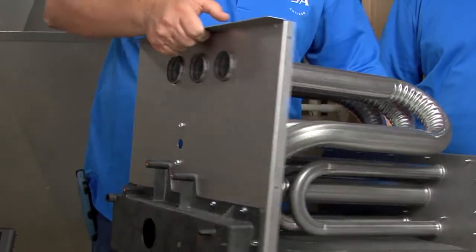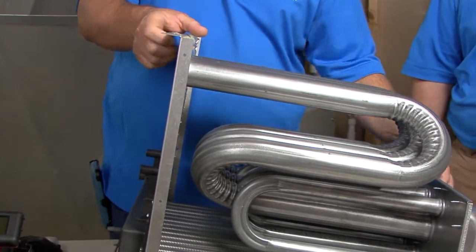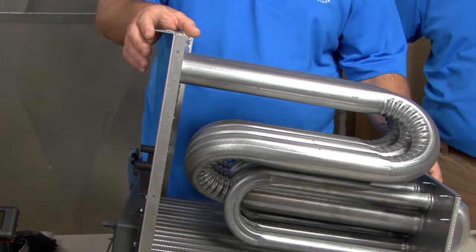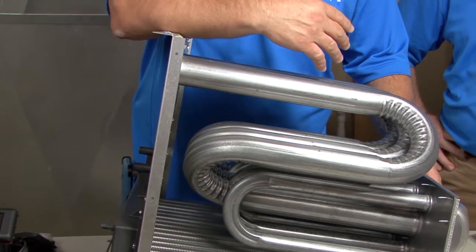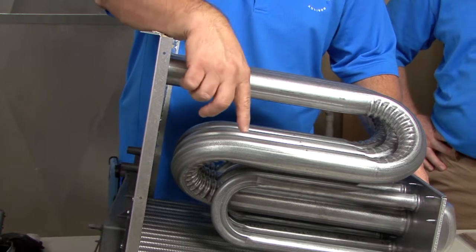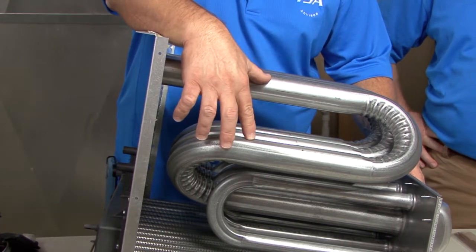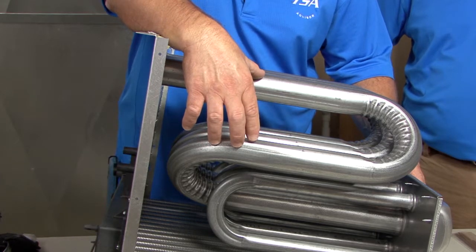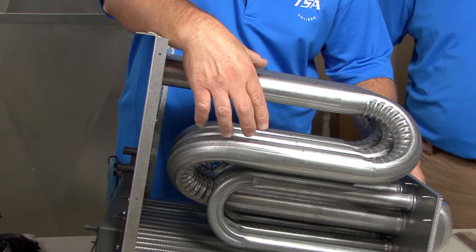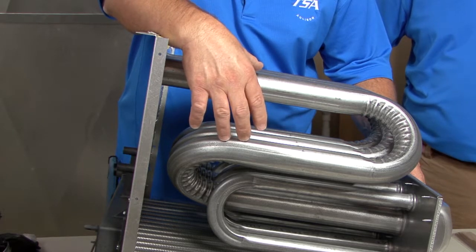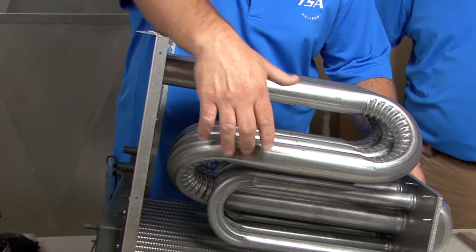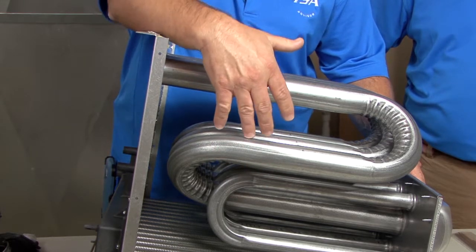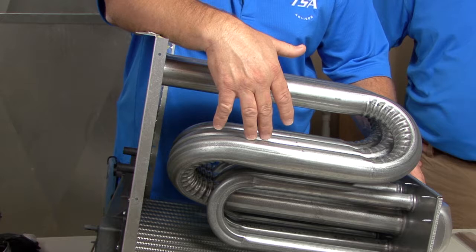So with that said, I'm going to focus back on the heat exchanger a little bit. I'm going to turn this heat exchanger around and see what we're actually trying to get out of this test. Once we've got the smoke in there, we've got air blowing through the heat exchanger. So if you've got any kind of a breach, hole, or crack in any of these primary tubes, now we're going to do the smoke to each tube individually on the front side of the heat exchanger. If we've got any kind of a breach, crack, or hole, the main air blower is blowing air across this, and it's going to blow air into that breach and affect your smoke.